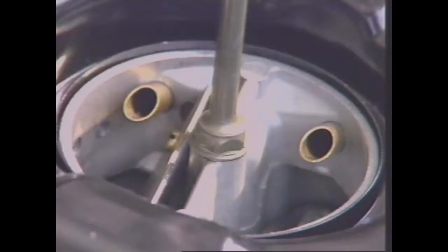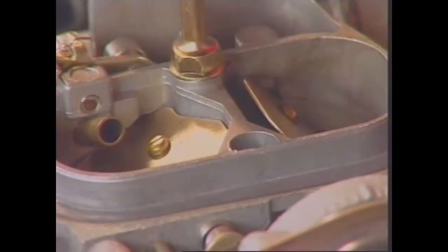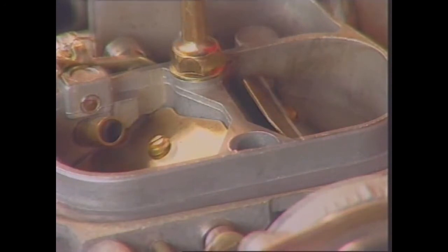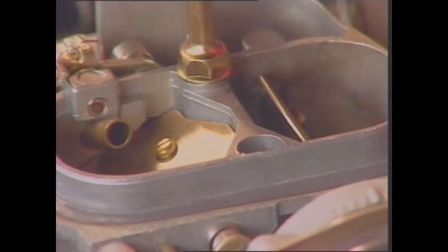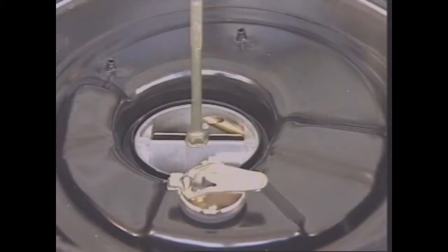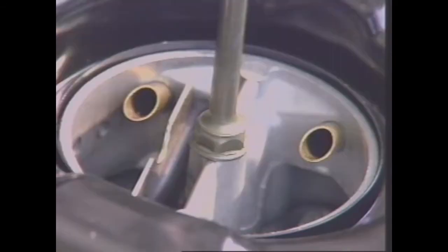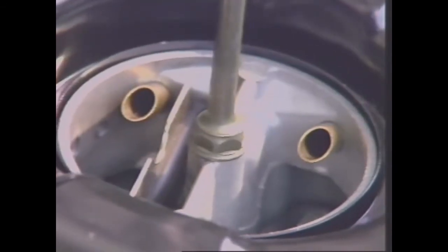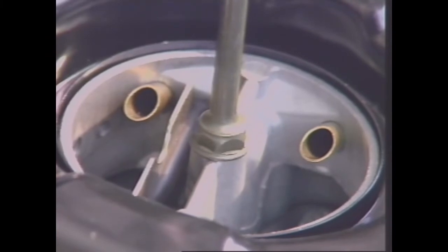The choke can be controlled manually by a cable that operates the valve. Most are controlled automatically, so that the valve is closed when the engine is cold and opens progressively as the engine warms up. When the engine is warm, the fuel drawn into the manifold during starting vaporizes readily, and the engine can be started without the aid of a choke.